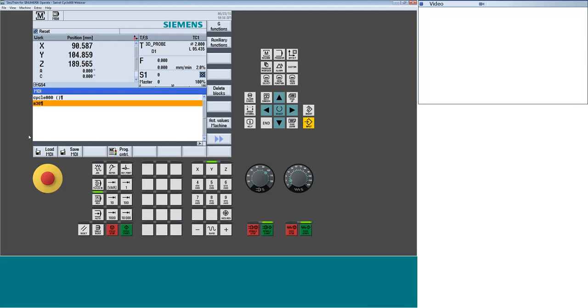This statement will also cancel whatever tool carrier is loaded. So you see my TC1 goes away there. That's very common. You see that type of syntax come out of a lot of CAM packages for shutting off tool carriers, and that's okay as well. The one thing this won't do is retract the head or anything, just cancel. So if the head was in some other location, I would have to manually start to move things out.